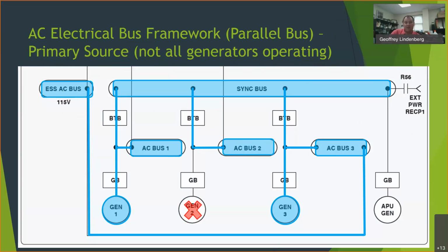They'll still be in phase. Now, it has its advantage in that way, is that we don't have to wait for contactors. With a split bus system, there is a slight delay, a slight trip where you'll see stuff kind of as those contactors switch over. But the big disadvantage with a parallel bus system is that they are connected all the